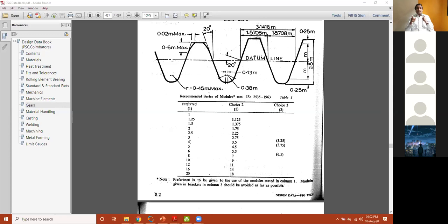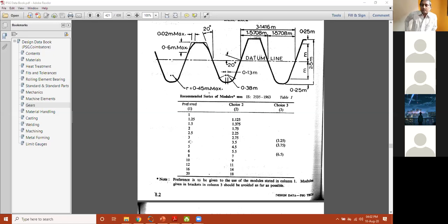Now here there is no need to calculate the beam strength, because there is a failure of the gear tooth in wear strength. So we will just find out the wear strength on the basis of increasing the module to 4, and accordingly, if there is a requirement of changing the FD, we will do that and see whether the design is safe or not. Okay, so find out FW and FD with the increased module as 4 and tell me the answer. I'll wait till then.